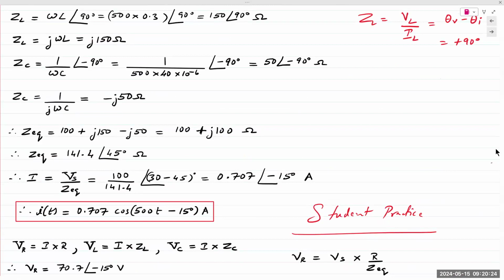Omega is obtained from the voltage source. Remember that the inductors, capacitors, and resistors will affect the amplitude, meaning the y-axis of the voltage source or current source is affected, and the phase is affected because there's a phase difference for an inductor and a capacitor. But nothing happens to the frequency. The frequency is not changed. Frequency remains exactly the same as the source.